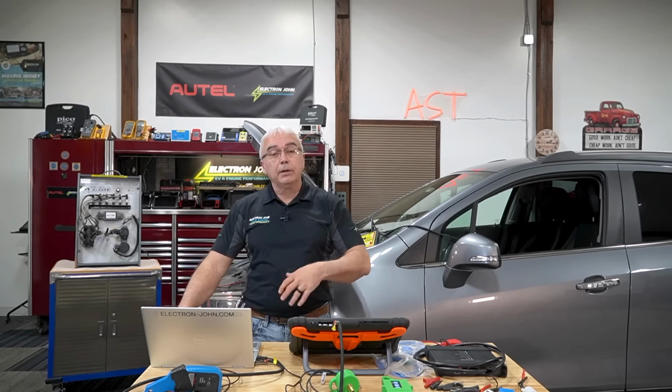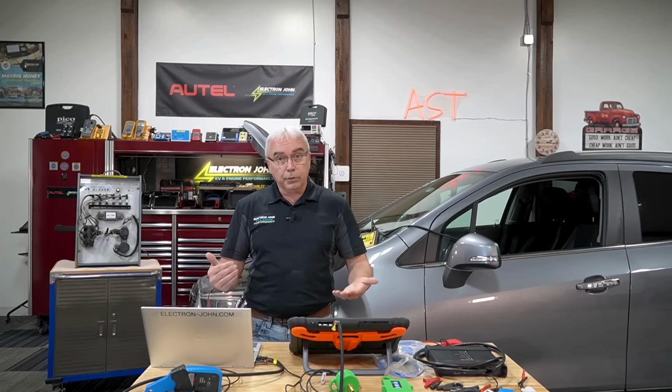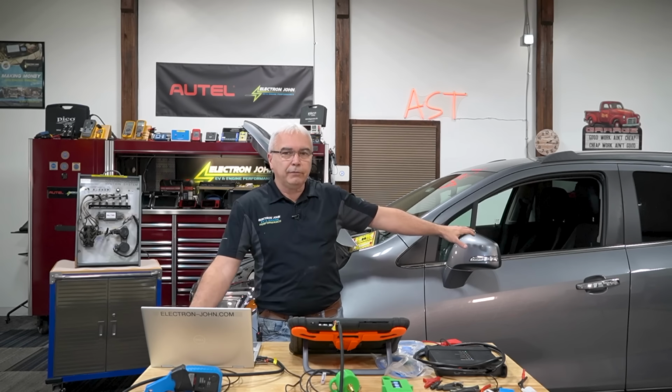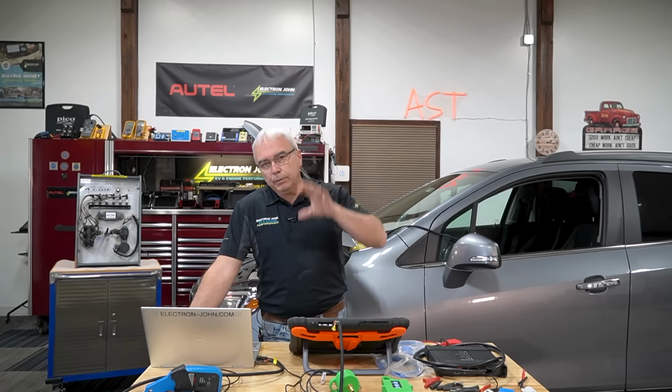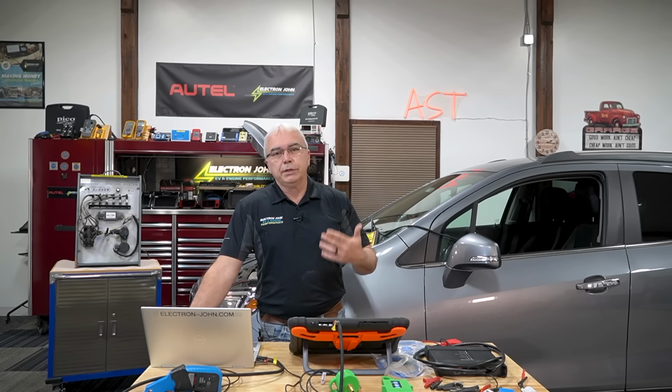Now before we get too much further ahead, I always want to back up a suspicion, right? So we'll use the first one, the temperature, as an example. If I thought, looking at that scan tool with the intake air temperature sensor, that I had a restricted exhaust because that temperature was too high, I'm not going to stop there. I'm going to look at other PIDs to help me verify that that is in fact the problem. Because what I'm basically trying to accomplish is, when I get out of the driver's seat and start doing pinpoint testing on the system, I want to verify and justify any time it's going to take me to do a series of tests.